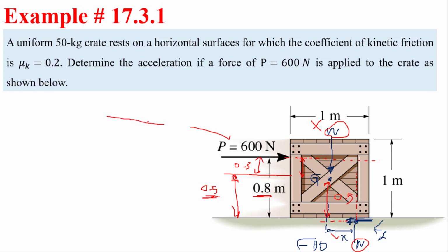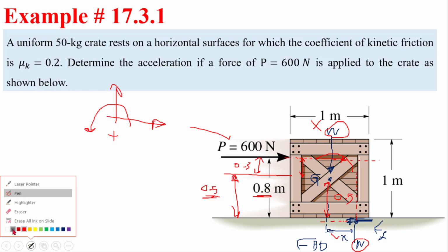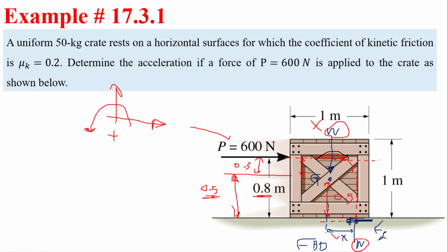Now remember the assumption that we started with, that counterclockwise is positive. Okay, so let us see. If you use your right hand, imagine that here is the force, and you put your right hand, then you will find that this force will act a moment clockwise, so its sign is negative.